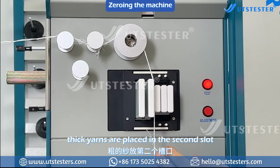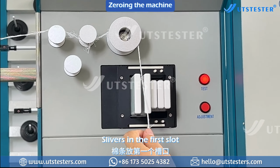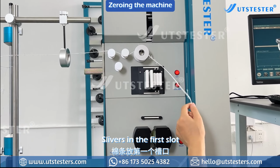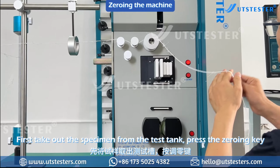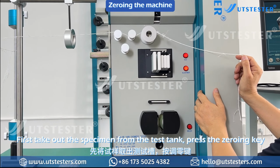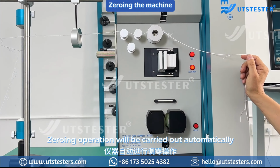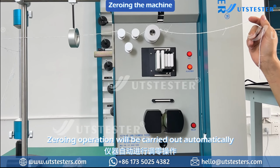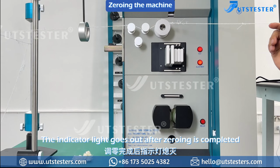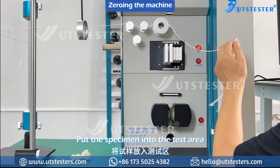Thick yarns are placed in the second slot. Slivers in the first slot. First, take out the specimen from the test tag. Press the zeroing key. Zeroing operations will be carried out automatically. The indicator light goes out after zeroing is completed. Put the specimen into the testing area.